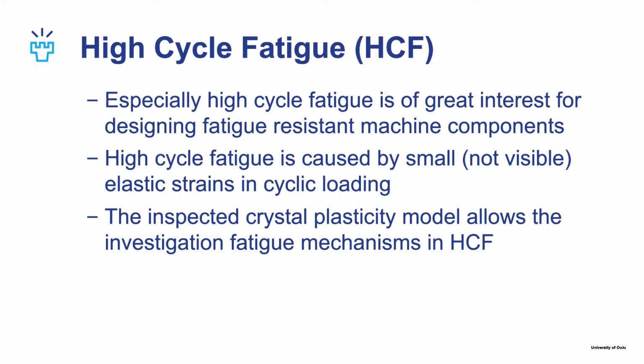Although the strain of the component is elastic, some plasticity still occurs in the material, which enables the fatigue failure. The crystal plasticity model we shortly look into allows the accurate investigation of these high cycle fatigue mechanisms.